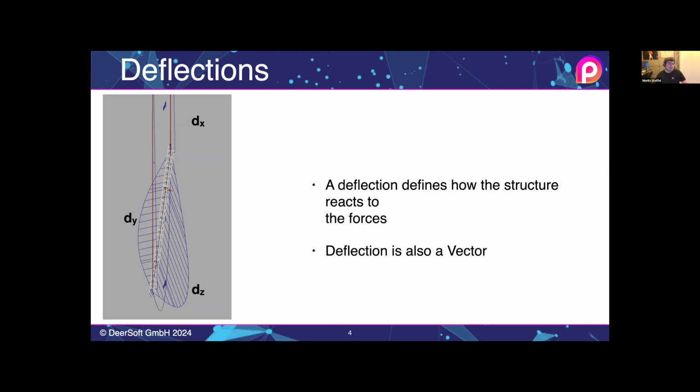Then you have the deflection DY. The deflection DY in this case goes to the side, but is also a little bit tilted, which basically means that the truss is a little bit tilted to the side. The other deflection, DX, is a deflection in the direction of the truss. This basically tells if a truss gets longer or shorter because of the compression.